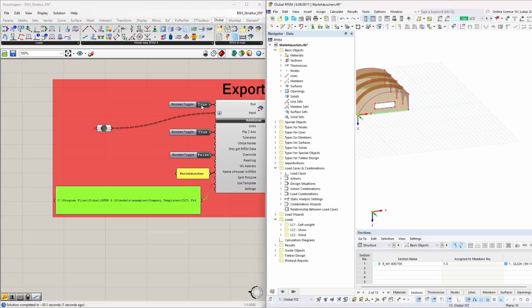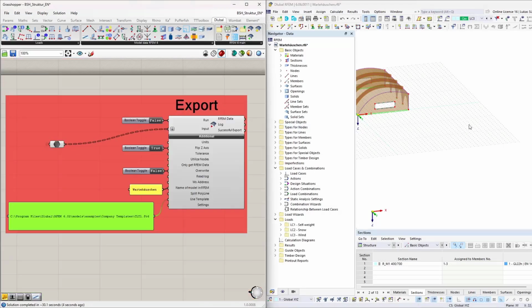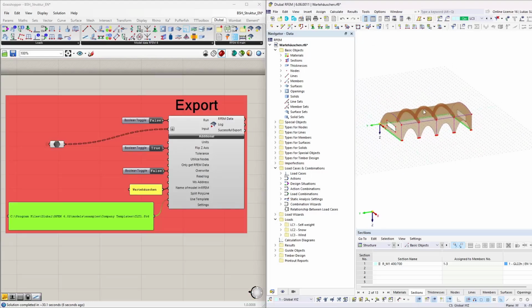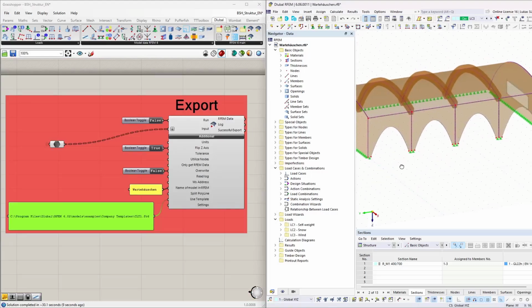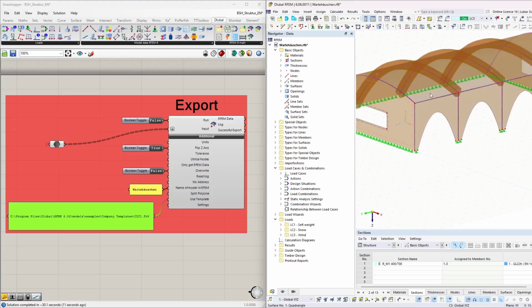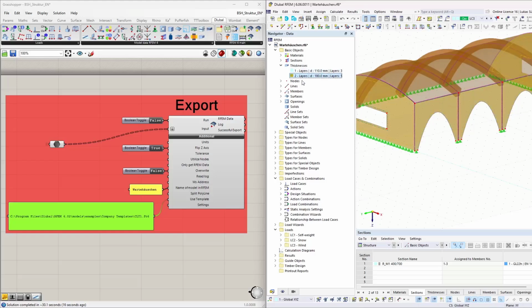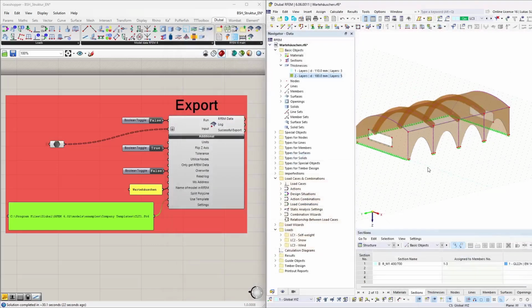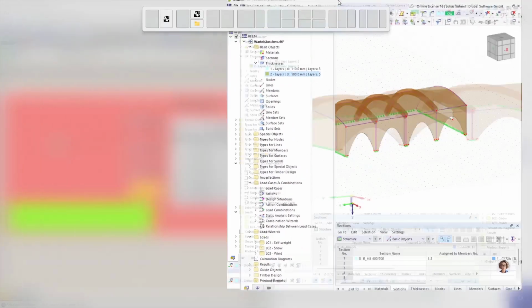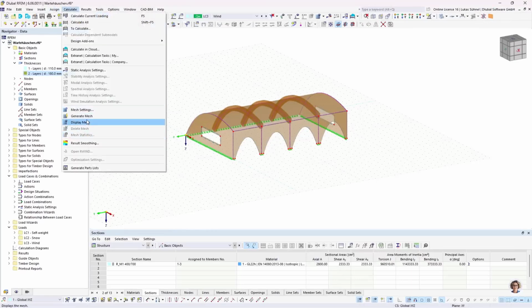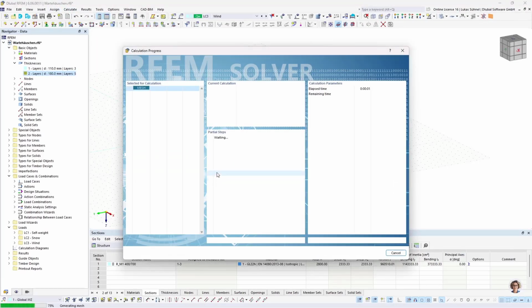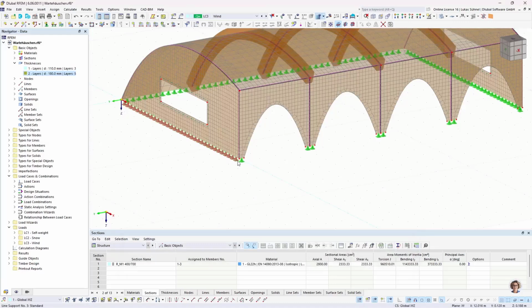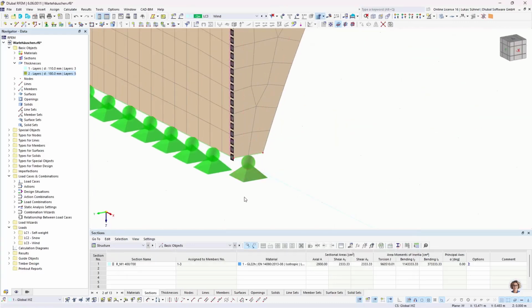All right. I disconnect the connection and I can see my file here. I have the geometry that I expected, my surfaces with the openings, my thicknesses with these layers that I defined before. Yeah, and that's already a file I can calculate. Let me maximize it for a second. I can generate the mesh. In this predefined algorithm, I used the mesh refinement of 0.2 meters. That's why I have just 2 elements and not 3 over the width.